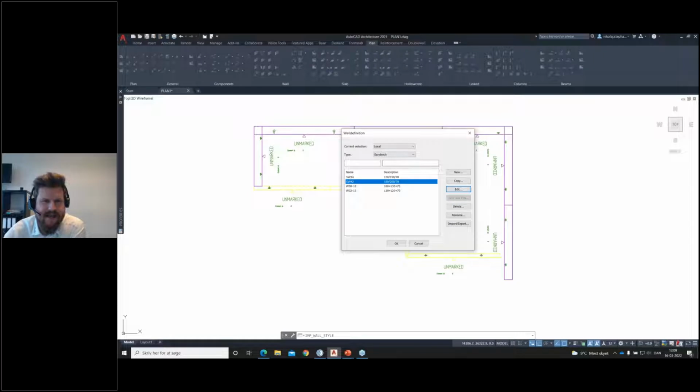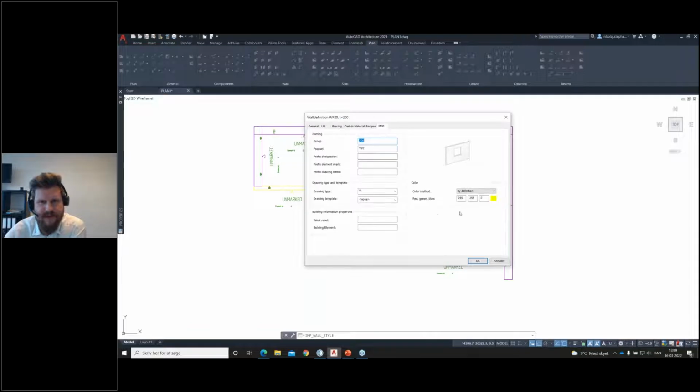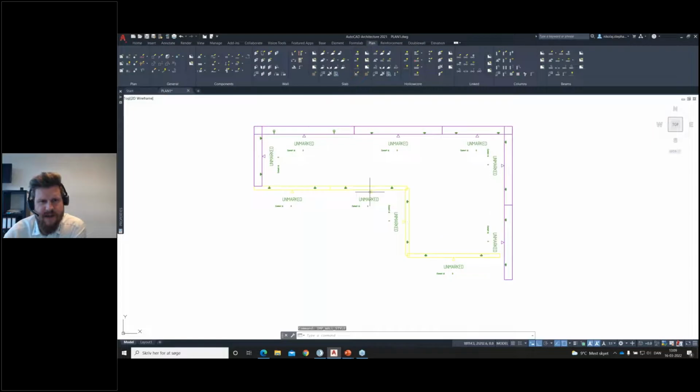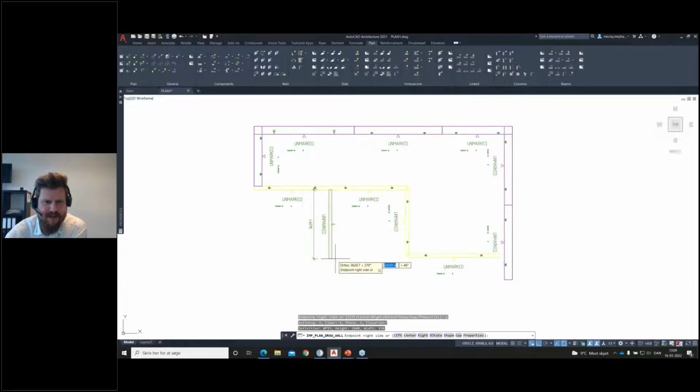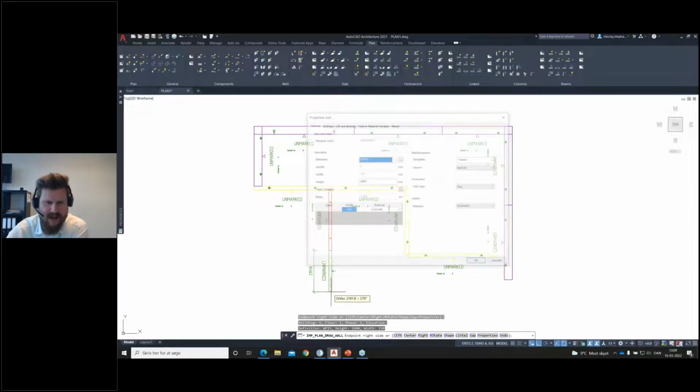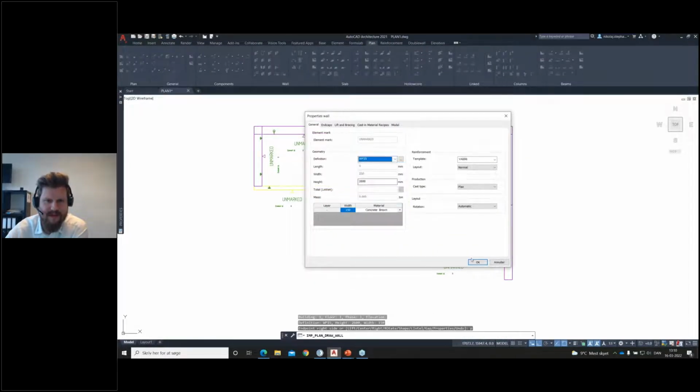And then again, it's the exact same case if we look into the standards of the walls here. We'll go into the common here. We'll check out the 20 mil one. So it's also colored by definition, and it's yellow. To show a little bit differently here, let's say we're drawing some other walls. This wall here is one size, but let me do some 15 centimeter ones. They're red. Let me do some 25 centimeter ones.